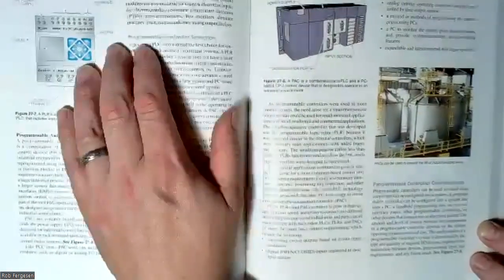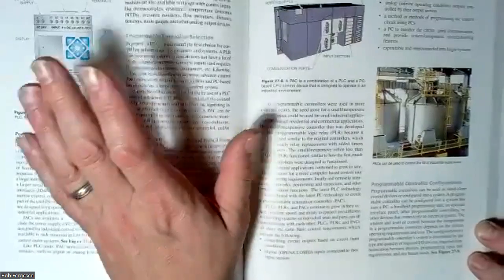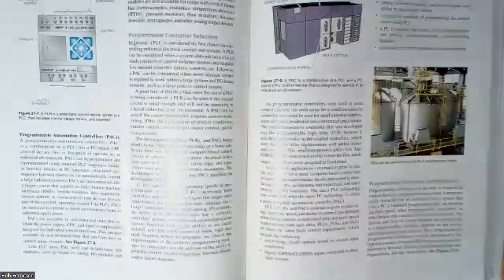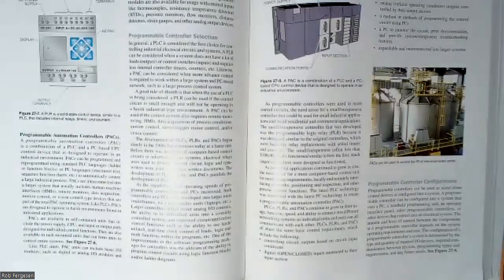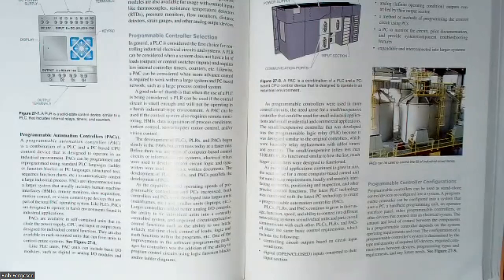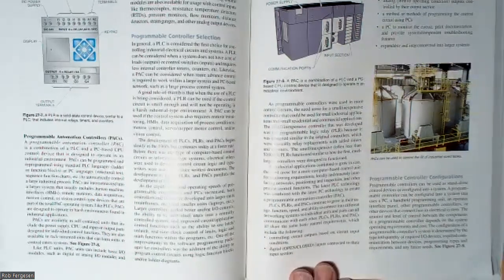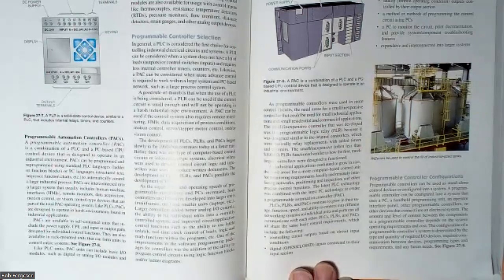Starting on page 600, though, they do get into some useful stuff, which is how do you size the programmable controller? Generally speaking, I/O is your count. It's your main count for sizing the PLC. The more inputs and outputs you have, the more processing you require, therefore the bigger the computer chip it needs to be, and therefore also the more racks you need for connecting in the I/O or the capability to communicate to multiple remote racks, remote I/O.